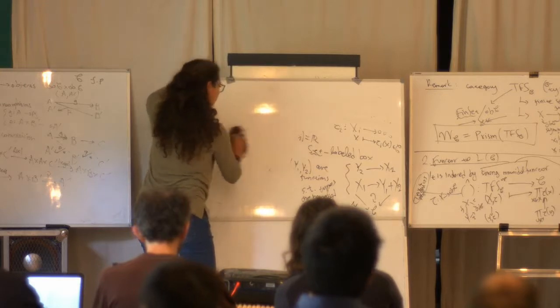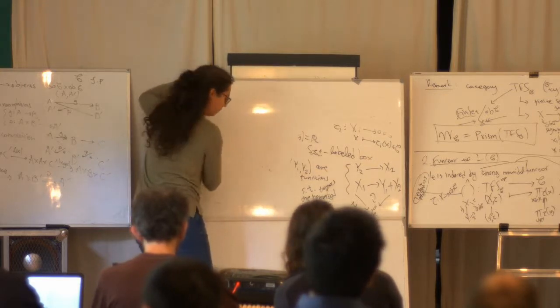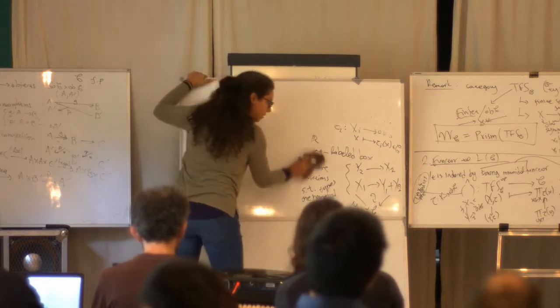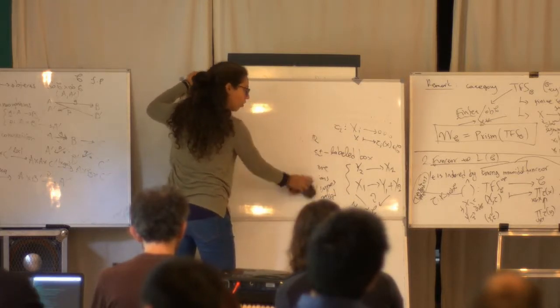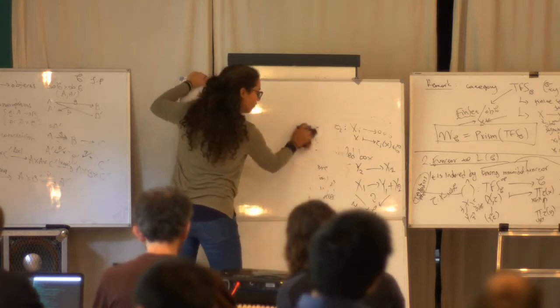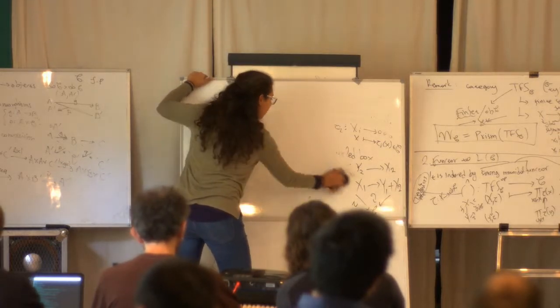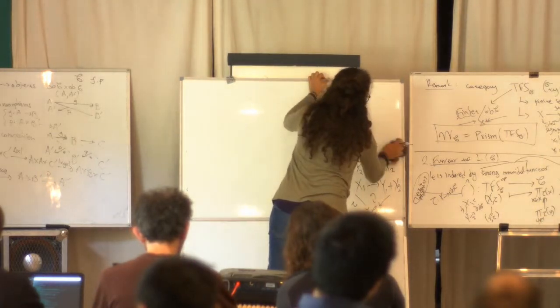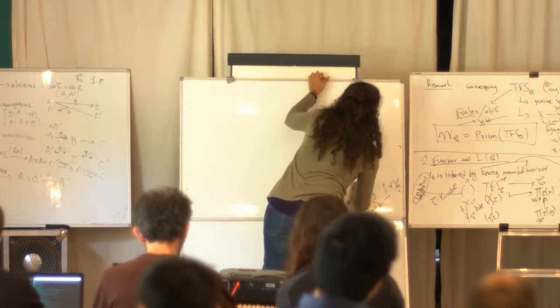So Moore machines are the ones with state, right? Yes, the state machine. Mealy machines also have state, but then the output depends on both the state and the input, not just the state. So Moore machines only depend on the state for what they output to the outside world, but Mealy also on the inputs.